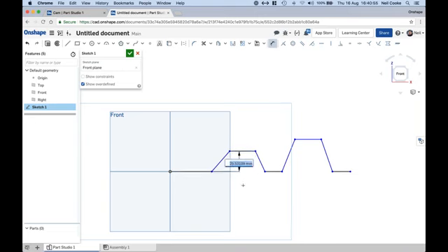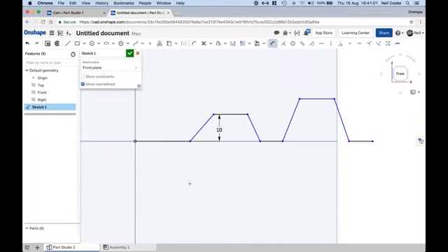So if you want to make sure that they're actually... we don't want to go at 25 mils, it's too much. Let's say 10 millimeters, and we can see that scaled the entire sketch, and perhaps let's say 15 here. And of course you can add dimensions on here, but this is essentially from 0 to 100% at this point. So if you want to make that 100 millimeters long and then that's 10, that's 20 to get percentage, then that's the way you would do it.